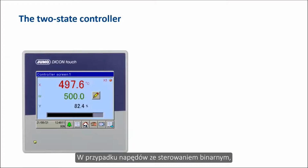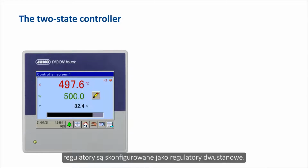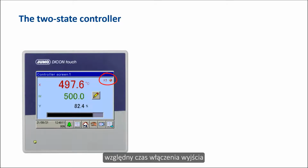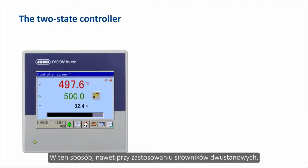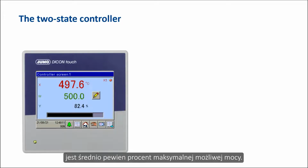For actuators with binary control, such as solenoid valves or thyristor power switches, the controllers are configured as two-state controllers. The controllers then vary the relative on-time of the output in proportion to the determined output level. This method of operation allows a percentage of the maximum possible power to be fed into the process on average, even with the binary actuators.